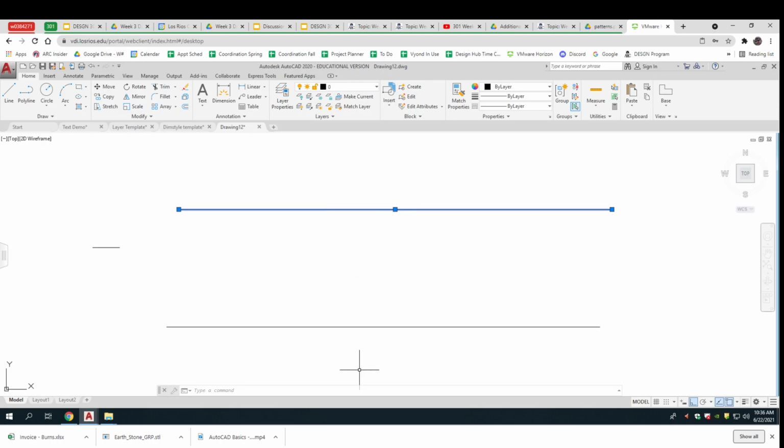Okay, so your default template is a drawing called a DWT, and you can set your DWT that you're open that way also. But when we start a new drawing out of the box, the ACAD.DWT is set for decimal inches, 4 places. And so when you start a new one, it always comes back to that. I'll show you how to do that in another spot, and maybe on Thursday on how to work with your DWT file, your drawing template, so that you can set that. But for now, just know that you can go back in and do it.